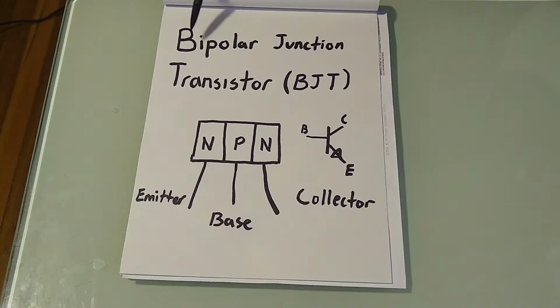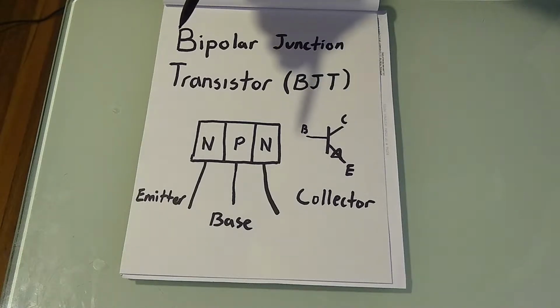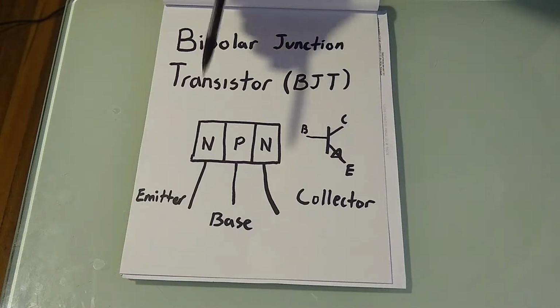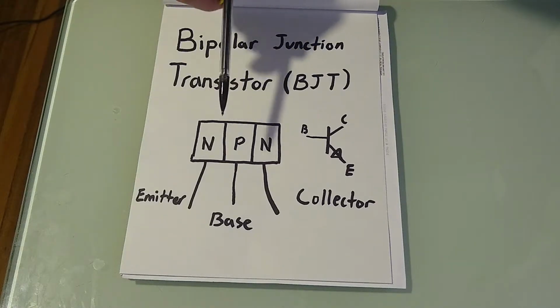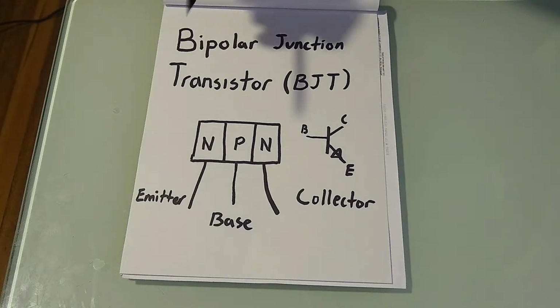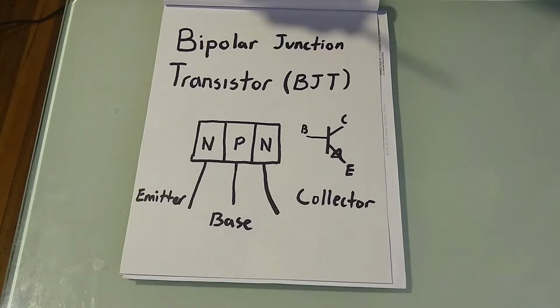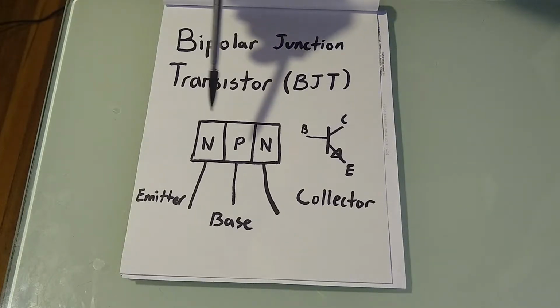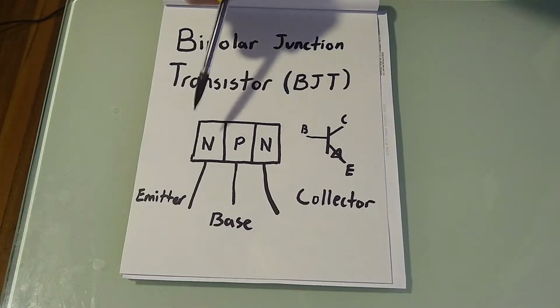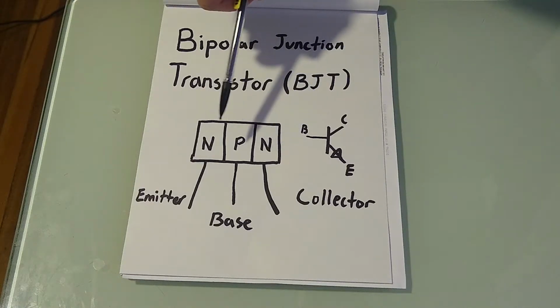Today we'll be talking about bipolar junction transistors, or BJT for short. A BJT transistor is formed by joining together two p-n junction diodes in series that share either a common P or N terminal. In this case, we have it sharing a P terminal, positive. Combining the diodes produces a three-layer, two-junction, three-terminal device, either NPN, which we have here, or PNP configurations.